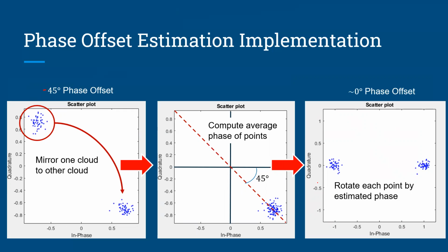If you know exactly what header the transmitter is sending, and you receive the header, you can take the Fourier transform of the packet header you receive, divide what you should be receiving by it, and that'll get you the transfer function, or the frequency response, I should say, of the channel.